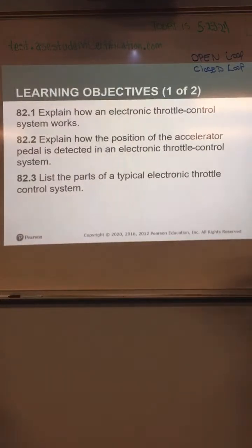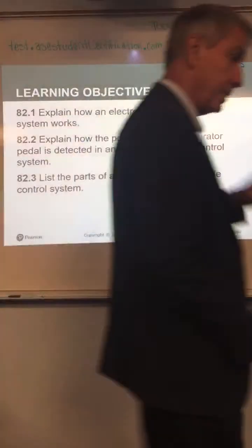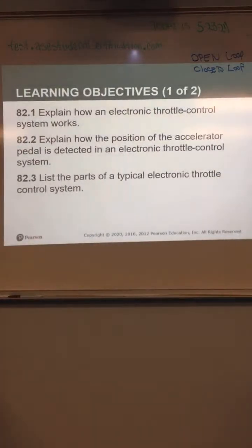And on the turbo applications, they actually have to have a stronger return on the throttle body, because the boost pressure tries to keep it open, because it's blowing air in there. Which is one of the reasons why, if you're driving a turbocharged car and you let off the throttle while it's under boost, it doesn't slow down right away. It takes a second. That boost pressure still has to go somewhere, or you'll hear the blow off valve blow the pressure off.